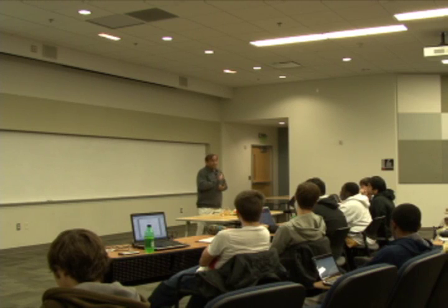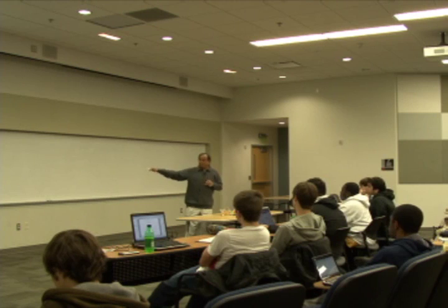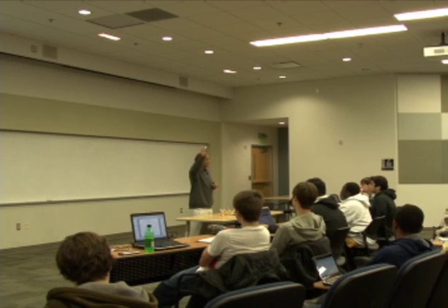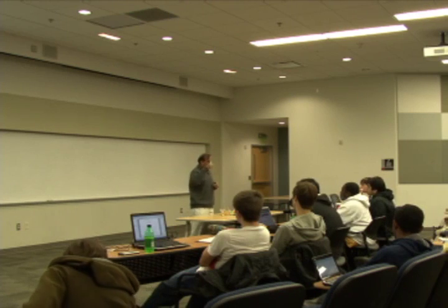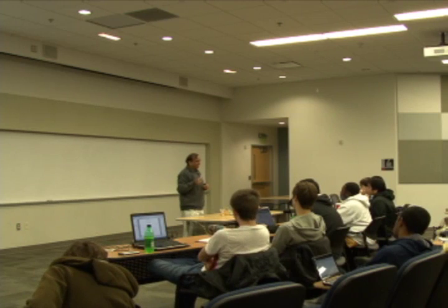No, it's not a 0 onto the bus. Remember that the output of this is coming from the data path in a particular register called the Z register, and we are clocking the register only when we need it, right? Only in the BEQ instruction we are clocking the register, otherwise we are never clocking it, and therefore the output of the Z register is always 0, right? It's guaranteed to be 0 except when we explicitly clock it using the load Z bit, right?